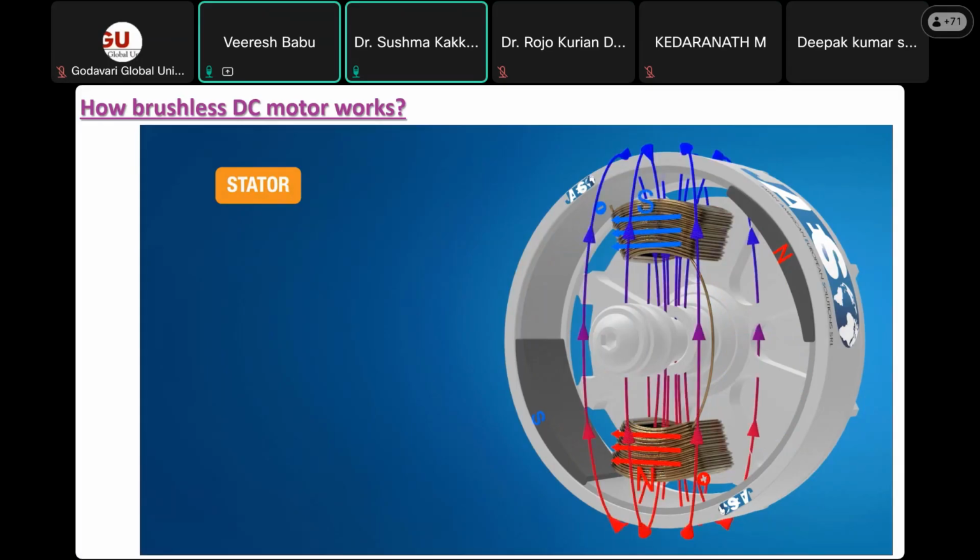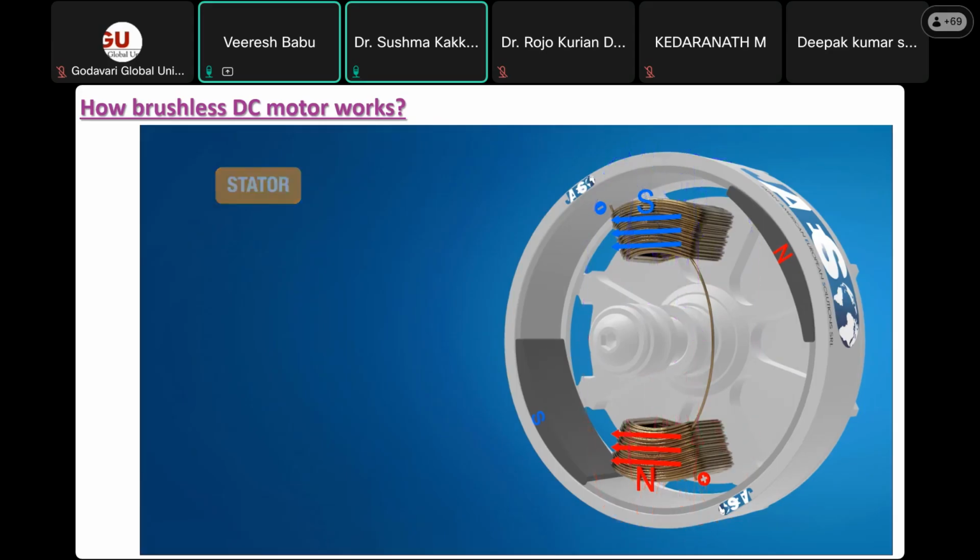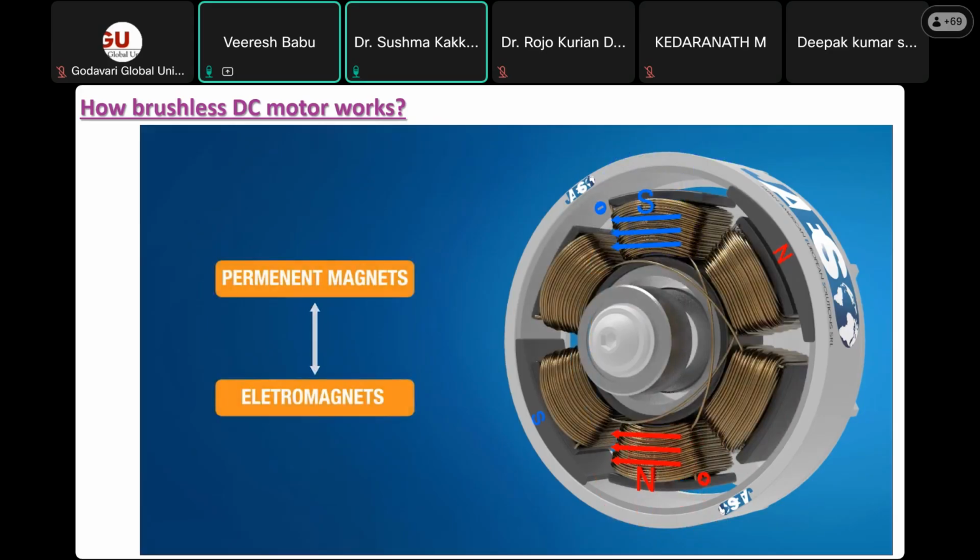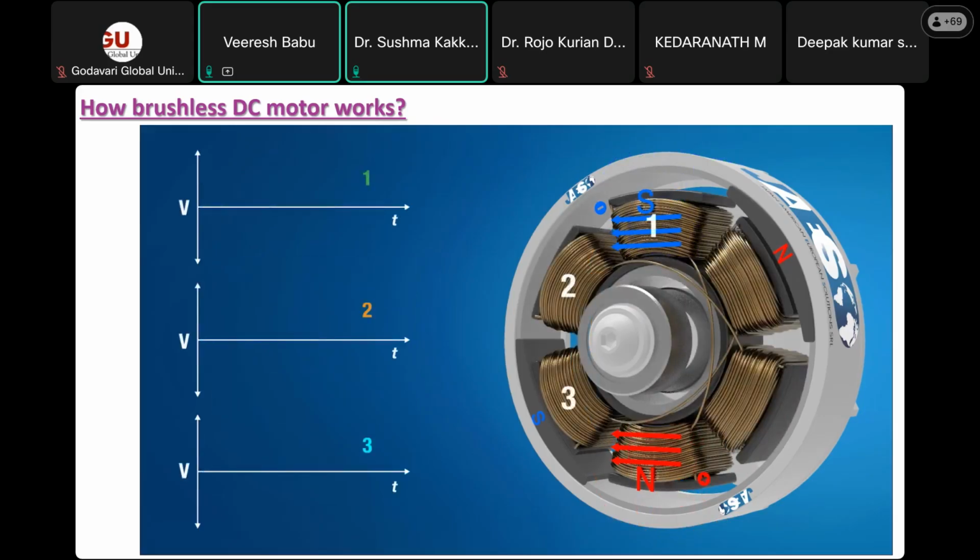There is a precise sequence of excitation of the electromagnets which imposes to the permanent magnets an angular movement, which is always in the same direction, and it is as constant as possible under the same excitation. Obviously, the sequence is cyclical, and the rotor continues its rotation until it's powered, repeating the sequence from time to time. To be more specific, the sequence of excitation of the electromagnets inside the stator is such that the magnets of the rotor are attracted to the electromagnets without ever reaching them, as the excitation is always and only of those coils, not yet reached.